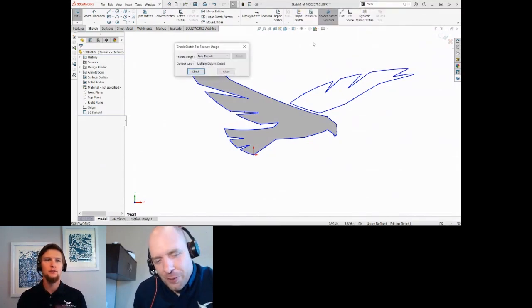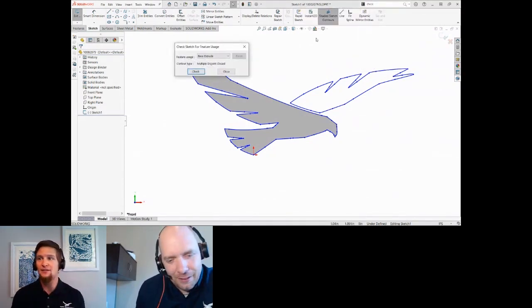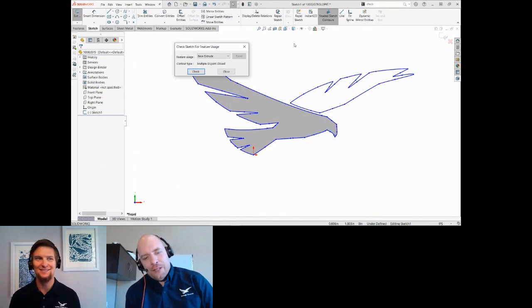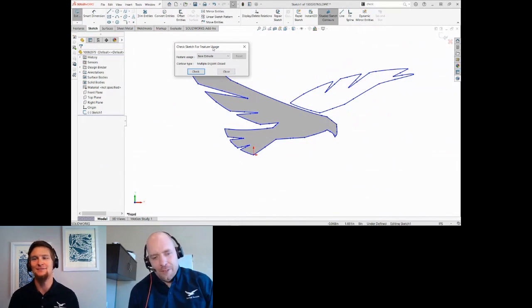Can I tell you what I used to do in a situation like this? Another kind of embarrassing thing. I would do a right click and select loop, and then do a fit spline on it. Which could be a good thing because you get nice smooth edges, but if you don't want that, then there might be some places to not use that for sure.